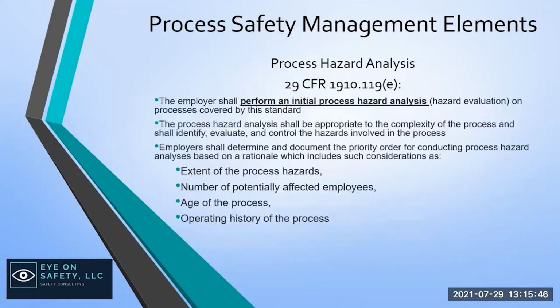Your process hazard analysis. This is kind of the backbone to the PSM element or the PSM standard. Basically, this is bringing a team together, and I'll go over the requirement of who all needs to be there. But this is bringing a team together and analyzing and walking the process and looking at every aspect of that process from start to finish, and basically evaluating, what are the hazards?